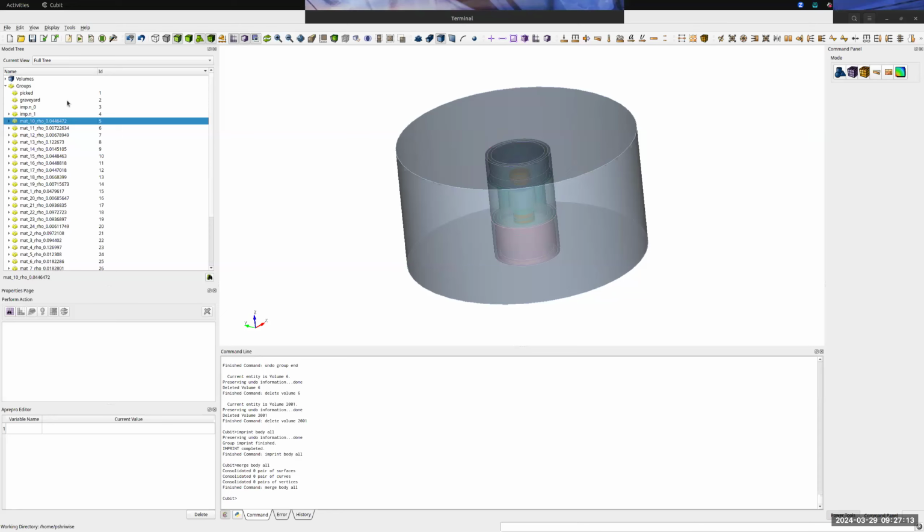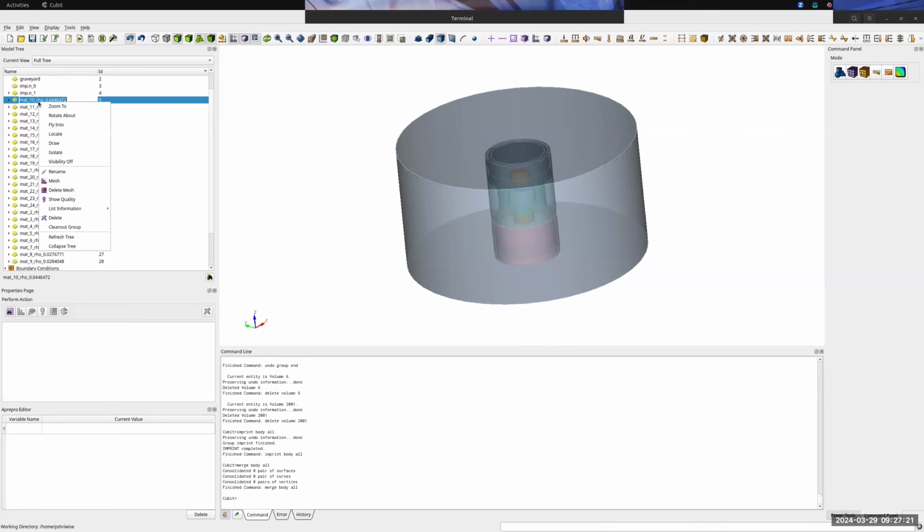a Python script. And so this is going to be kind of an example of a generalized operation for taking this legacy DAGMC naming scheme and updating it to one that DAGMC would recognize if we were to use the ad hoc or UW-based DAGMC plugin that you can enable within Cubit, but is not the integrated version. And so what that format would look like is something more like this,